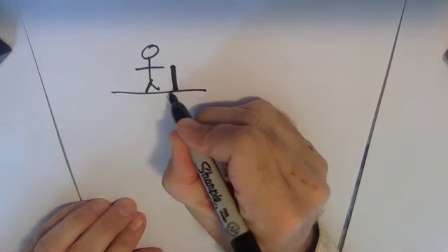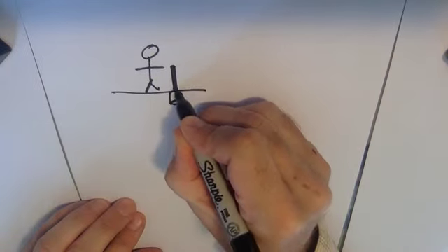And so what I'm going to diagram for you here is a pretty simple setup that was designed to allow you to calculate hydraulic conductivity on really small sections of material. So what you do is you walk out in somebody's field, and you shove down into the ground a big metal pole, and at the end of it has an open cylindrical sort of canister, and it takes a sample of the dirt, right? The dirt gets shoved up inside this thing.